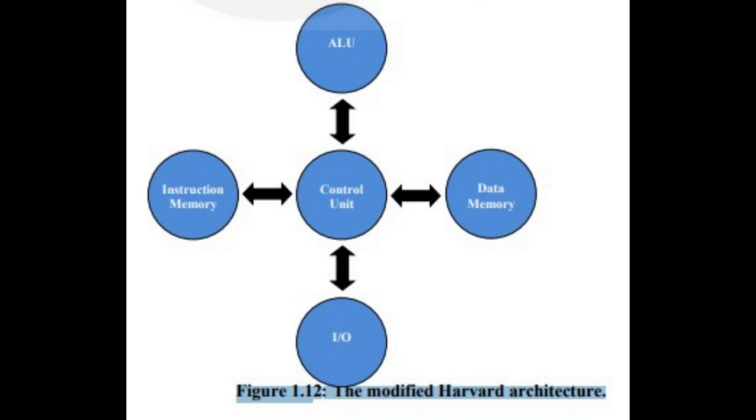Address. The modified Harvard architecture is similar to the Harvard architecture and has a standard address space for a separate data and instruction cache. It has digital signal processors that can handle audio and video data efficiently. It also has microcontrollers, the processing circuits that process a small number of applications, and has small data memory and speeds up processing by performing the commands and data access simultaneously.